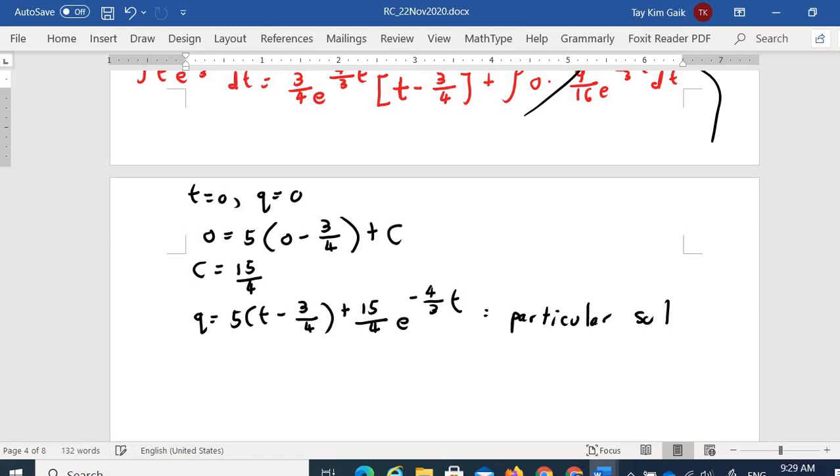You can check it. As we know, I is actually dq dt. That's the same RC circuit. If we solve in terms of q, we get here. Initially we solved in terms of I. So we are going to check whether the I we get from dq dt will be the same as what we modeled for the RC circuit directly in terms of I.